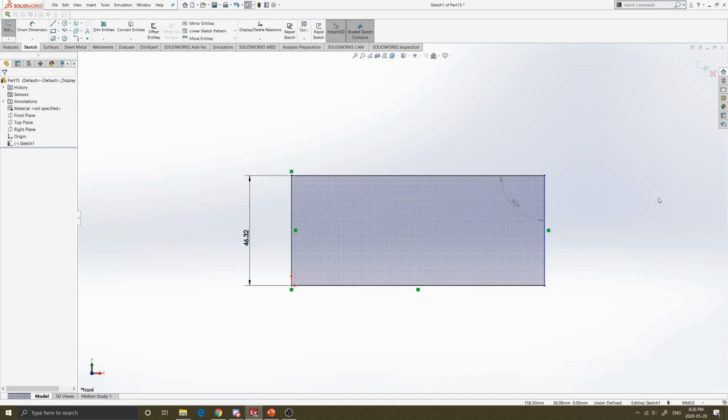When you want to design something, you don't want to over define it, because you want everything to lead to one answer, if that makes sense. If you know that this line is perpendicular to this line, then you don't need to say that this is 90 degrees, because it's already 90 degrees here, and this line is vertical to this one. So it's redundant. To make this true, you would have to delete this quantity. Oh, well.